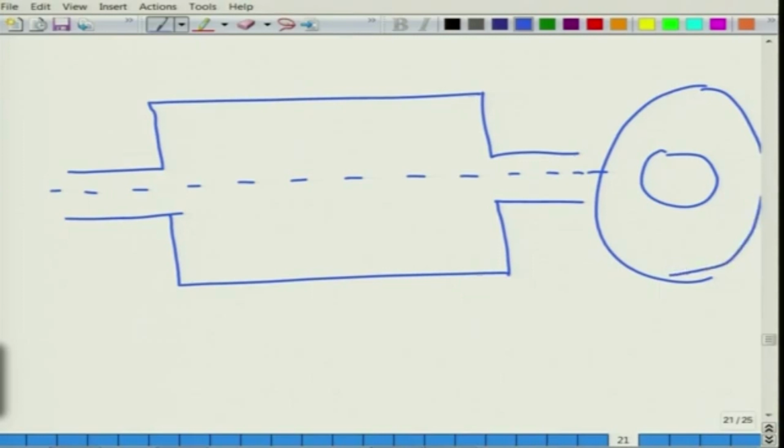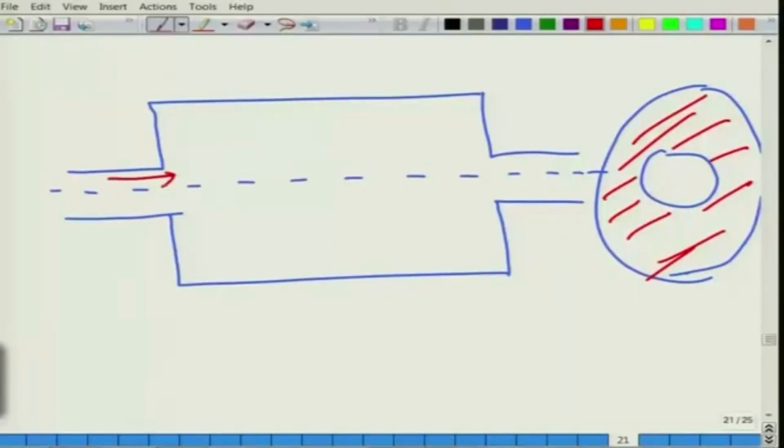So, the section can be elliptical or a circular thing. Shells are of circular cross section. They can also be elliptical, but circular are the ones that are more preferred because they have less breakout noise, they have more rigidity like I was mentioning. And this is the inlet port and this is the outlet port. I will call this point as 1 just at the interface, but within the inlet pipe, and this is the point 2 which is just in the chamber, but at the interface of the port in the chamber. This is point 3, this is point 4, inlet, outlet.